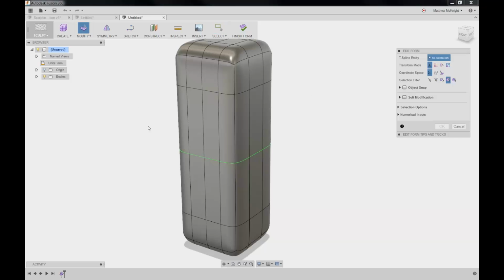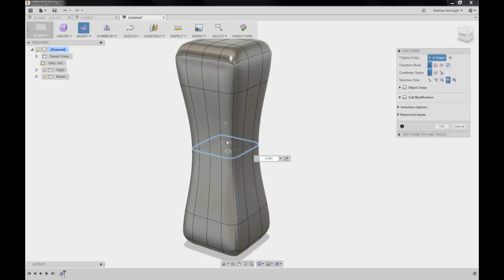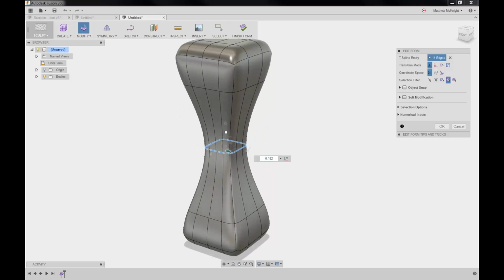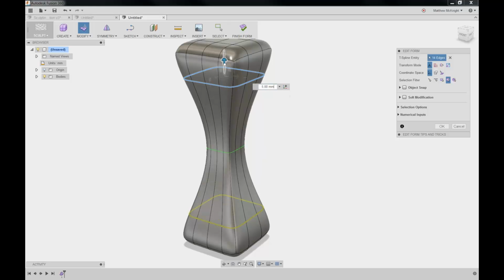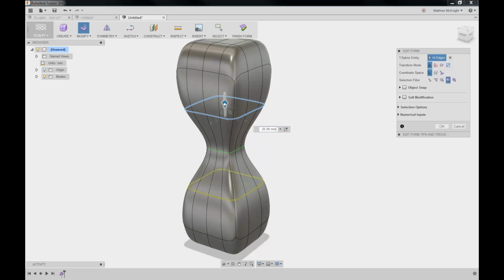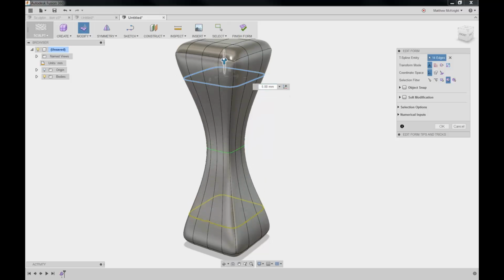So I'm going to hit my modify command, group select a whole string of entities, and let's just hit the scale icon, and you can see here that we can quickly and easily then scale that object around the center plane very, very quickly. So I've got a completely different object in a few moments. Likewise, if I wanted to, I can drag and manipulate this geometry upwards and downwards to then give us some shape that we wanted to.